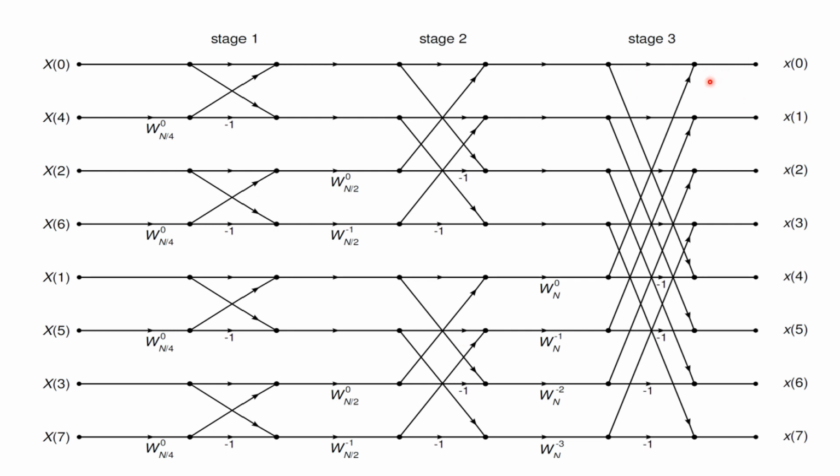And the third stage will comprise one single 8-point butterfly. For that we need to have 4 twiddle factors: Wn0, Wn1, Wn2, Wn3. So Wn0 means W80, and W81, W82 and W83. So these are the stage 3 twiddle factors, and we can compute this DIT stage by stage in a separate manner.